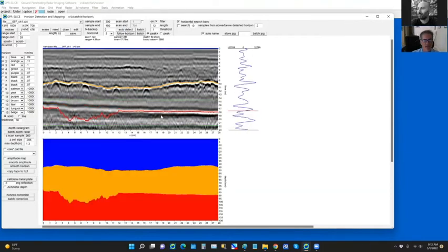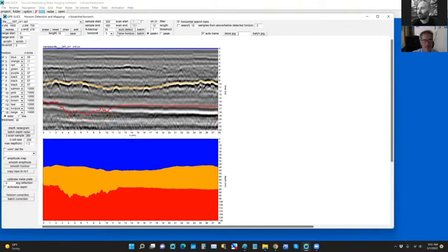And I can edit that, but let's say even though I'm detecting the white, I want to move up the horizon to be launched at the beginning of the black, or the beginning of the initial part of the pulse. I can actually come over here and put in a value and detect it, and it'll move it up that number of samples. Let me go back down to like 30.